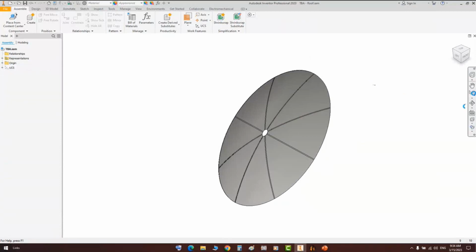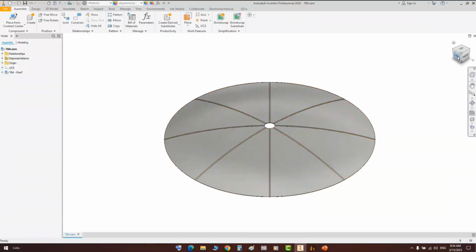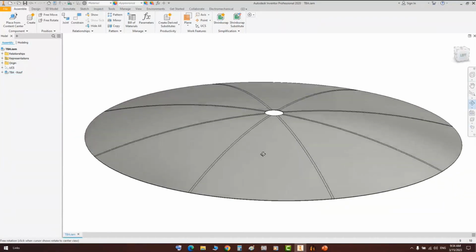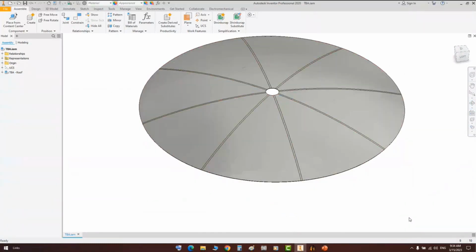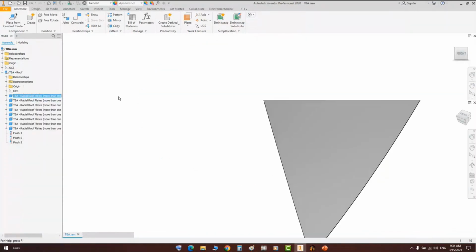Okay, and after creating the assembly, it will be assembled to the final assembly. And here you have the radial segments of the dome roof. And by the way, there is no option to get a flat pattern for the blades, which take a deformation on two sides like a dished head. But there is an option for unfolding in Autodesk Inventor. You can use it.